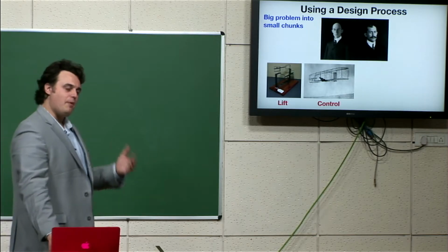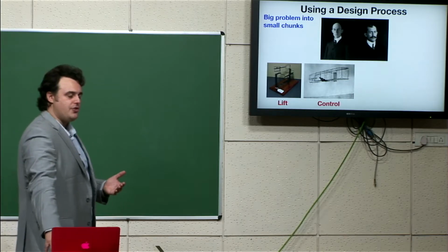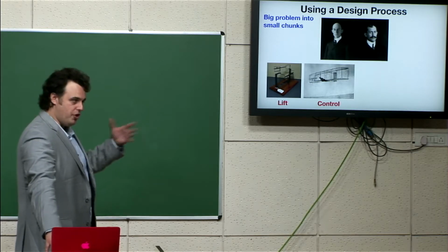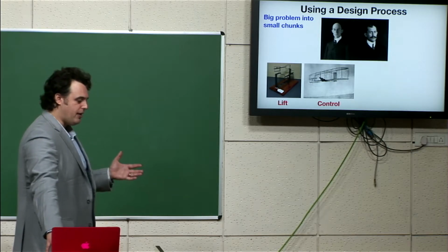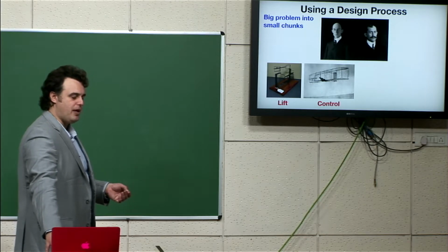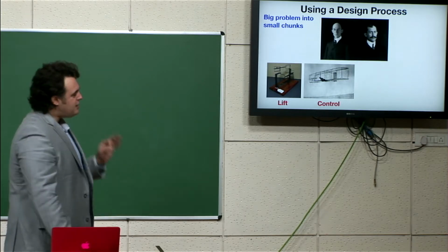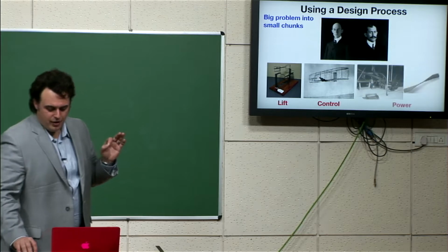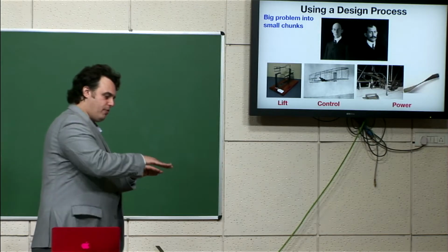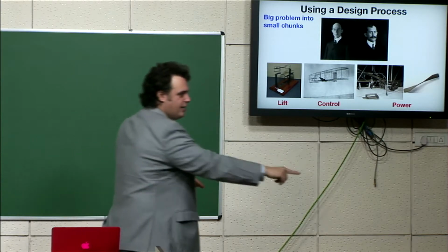Then, when it came to the propeller, the leading theory of the day was that airplane propellers would work just like ship propellers. So the Wright brothers, being good, diligent engineers, read all about ship propellers. And it turned out that there was really no theory behind how ship propellers were designed. People would just kind of design them by eye. And so the Wrights figured out that a propeller is just a wing with a changing angle of attack as you go from the root of the propeller out to the tip that's moving through the air in a helical pattern.